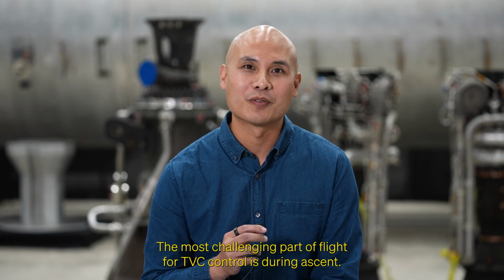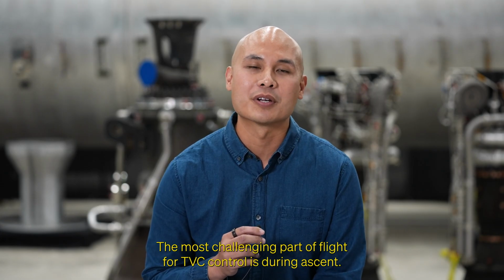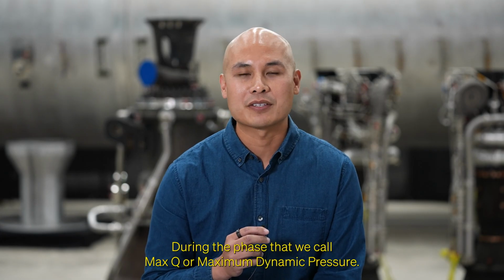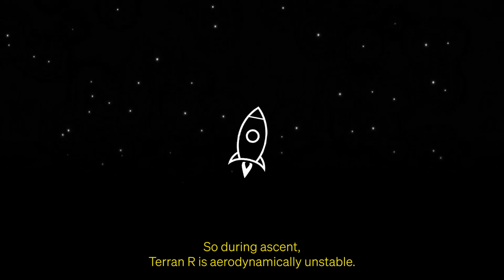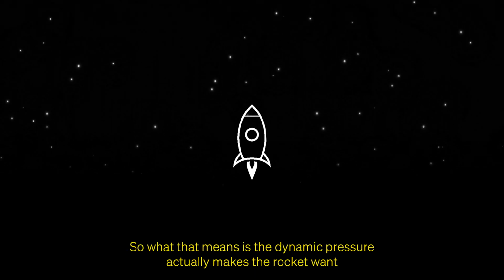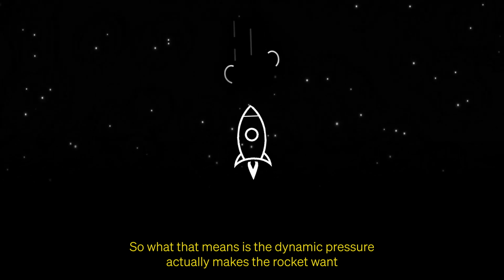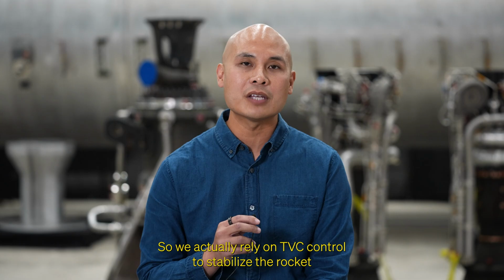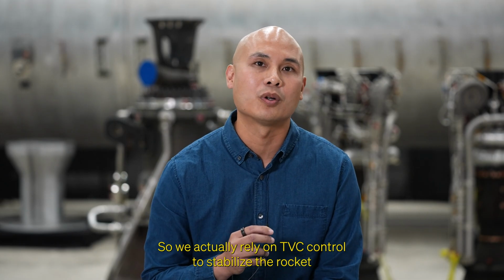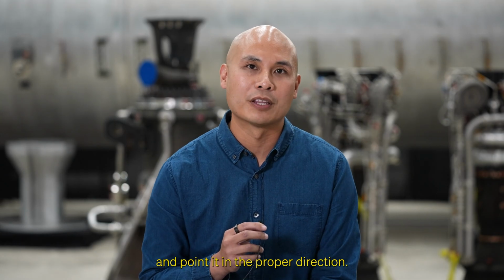The most challenging part of flight for TVC control is during ascent, during a phase that we call max Q, or maximum dynamic pressure. So during ascent, Terran R is aerodynamically unstable, so what that means is the dynamic pressure actually makes the rocket want to flip around and point with the nose in the opposite direction of the flow. And so we actually rely on TVC control to stabilize the rocket and point it in the proper direction.